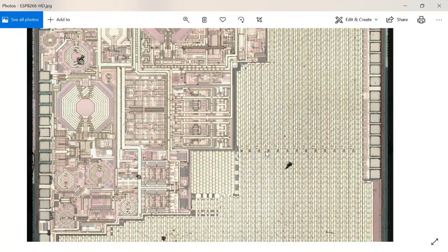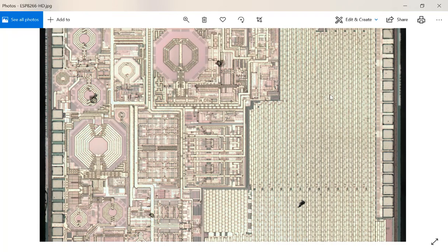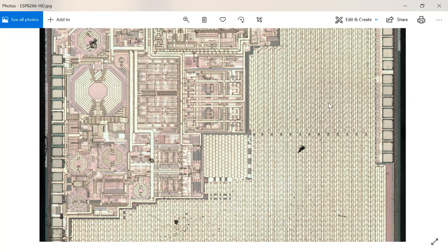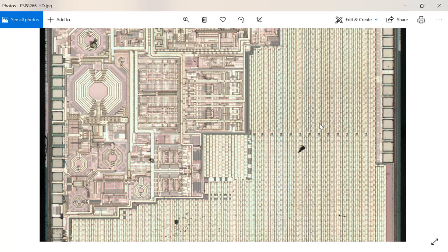That's why they place the top metal layer here to cover all the main stuff. But they cannot cover these ones because the coils are on the top metal layer as well. If you cover it, it's probably going to affect the inductance. So you couldn't do too much here. But these ones are just pure digital signals. Let's just cover it to protect the IP.